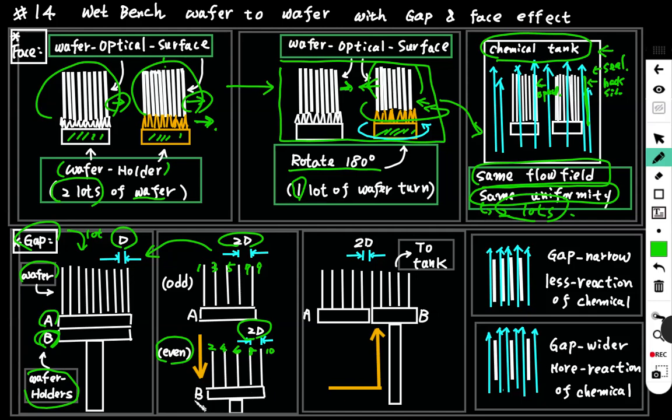And the wafer holder B keeps moving right and up to combine with wafer holder A and B now together, and lay the wafer together again with 2D's bigger gap, with the bigger distance between every wafer. Then lay together to the chemical tank to process.